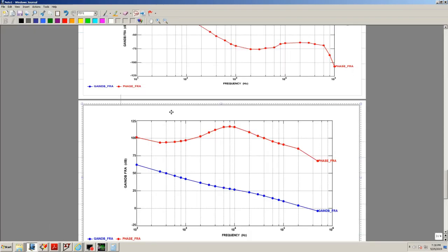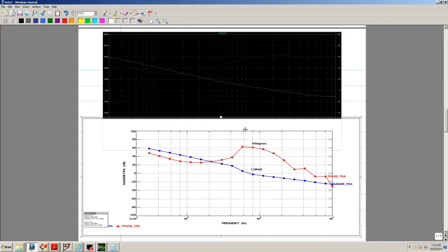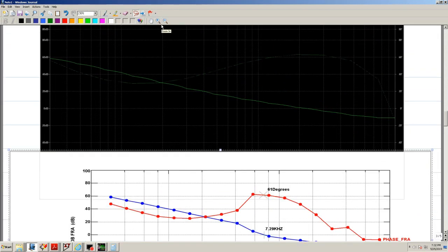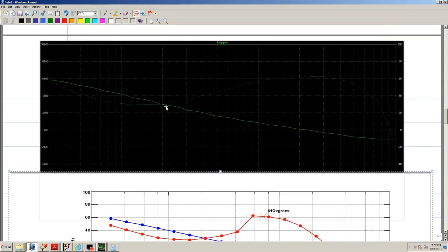and then let's examine this and see if I can zoom in first a little bit. Okay, so this is the Bode plot from the Ridley TopSPICE, and if you look here, the green solid one is the gain, and this dotted one is the phase. So here's the 0, and this is 20.